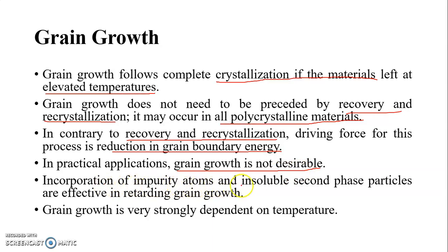Incorporation of impurity atoms and insoluble second phase particles is effective in retarding grain growth. Due to grain growth, we cannot get a precise material. In hot working operation, there is no precision of the work. Therefore, we prefer the cold working operation.